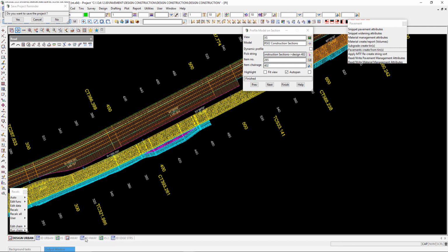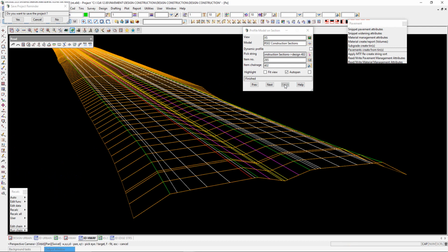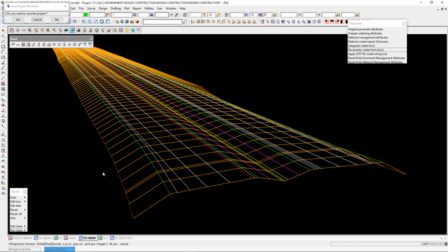We'll now look at the highway type job. So in that case here, we've got something that's similar, strings that create the actual design. Work's been done to take away any off ramps or side roads, and strings have been looked at to have a good naming convention, nice continuous strings that help in the creation of the pavement polygons, and also the continuation of the edge strings.